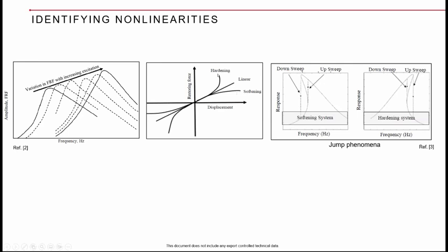that can be termed as softening or hardening. So generally, this kind of polynomial hardening, or contact stiffness, contact nonlinearity, or a change in the boundary conditions, a step change in the boundary conditions, like suddenly there can be a contact after a certain deflection, for example. So all these scenarios are nonlinear behaviors.